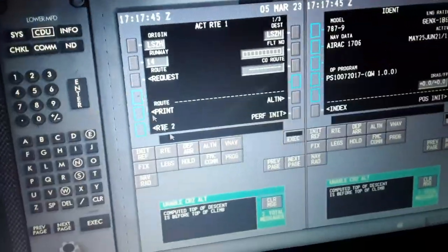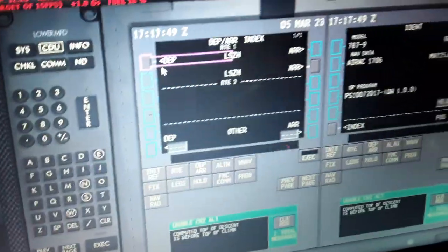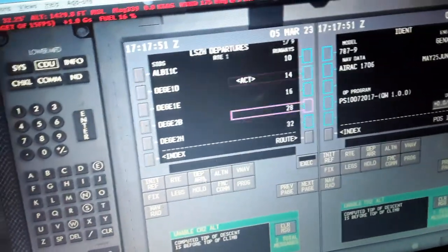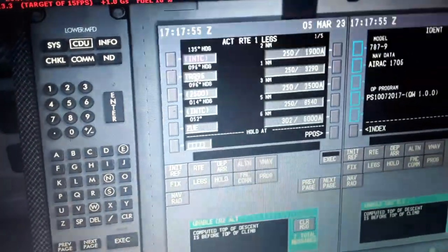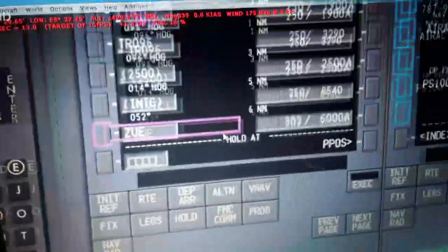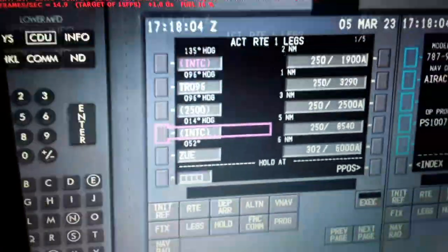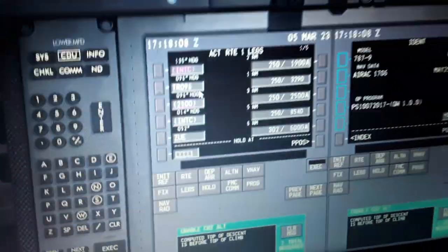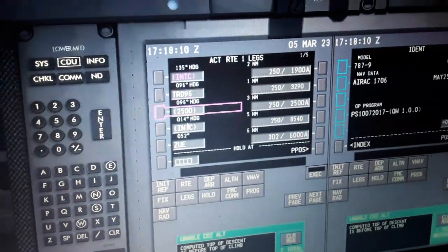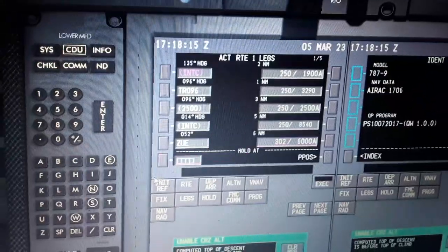and for landing. Departures and arrivals over here, select the departures from the airport over here, runway 14, then arrival. Then we have the creation of the flight plan using the SIDs, the standard instrument departure, waypoints and fixes, and the STARs. So you can see we have to cruise through these waypoints when we fly from takeoff. First waypoint, second, third, fourth, fifth. Here is 6,000 feet, the airspeed and the altitude constraint.